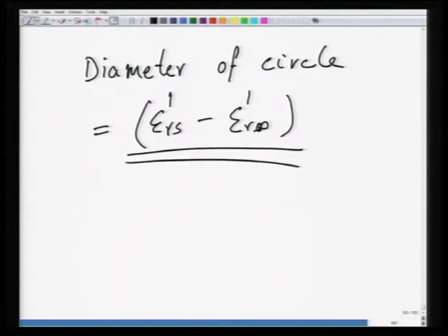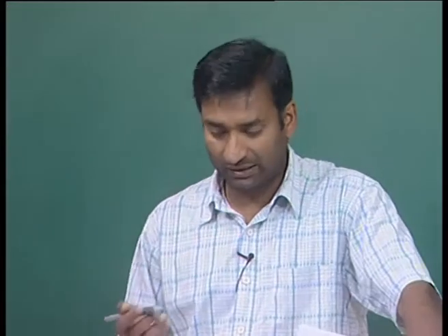So, a perfect dielectric material, as Kenneth and Richard Cole proposed, would look like a perfect half circle when you plot epsilon r double prime with respect to epsilon prime as a function of frequency. However, this is true only for materials which exhibit ideal behavior. In case of non-ideal behavior, this Debye equation gets modified, as Kenneth and Richard Cole showed, and we will write that in a minute.